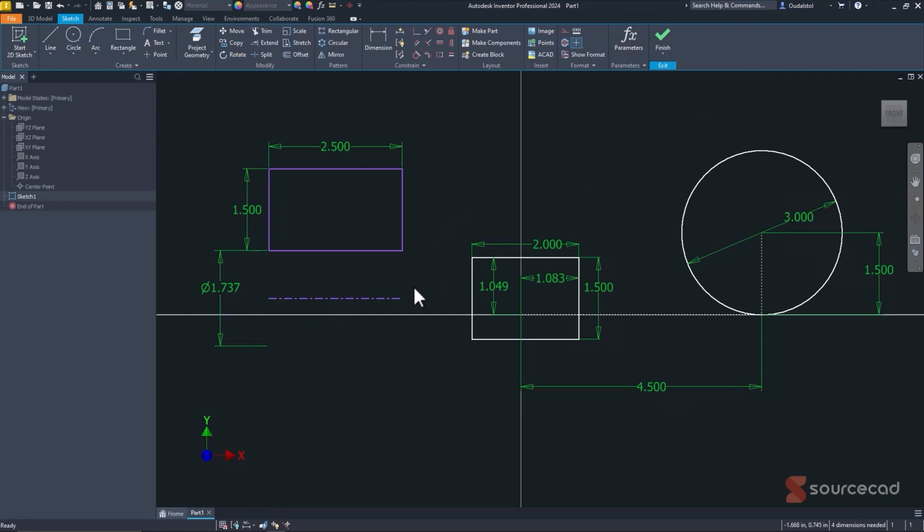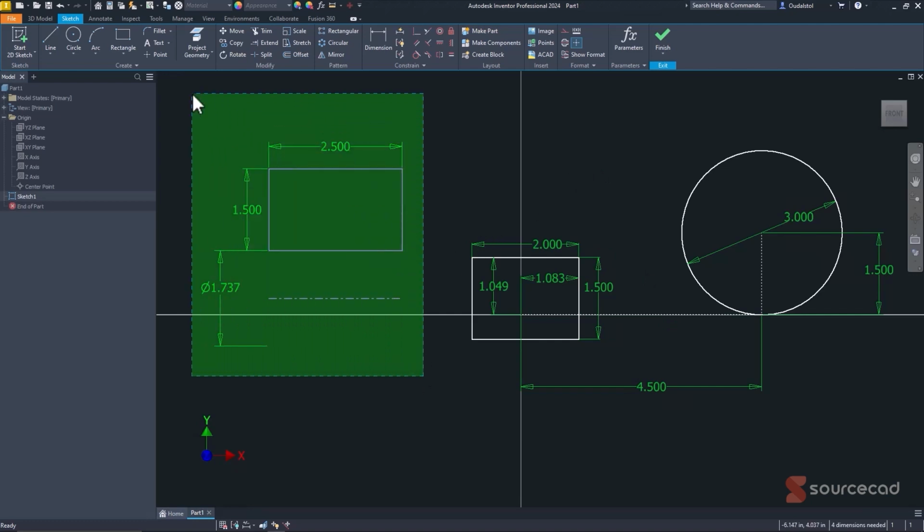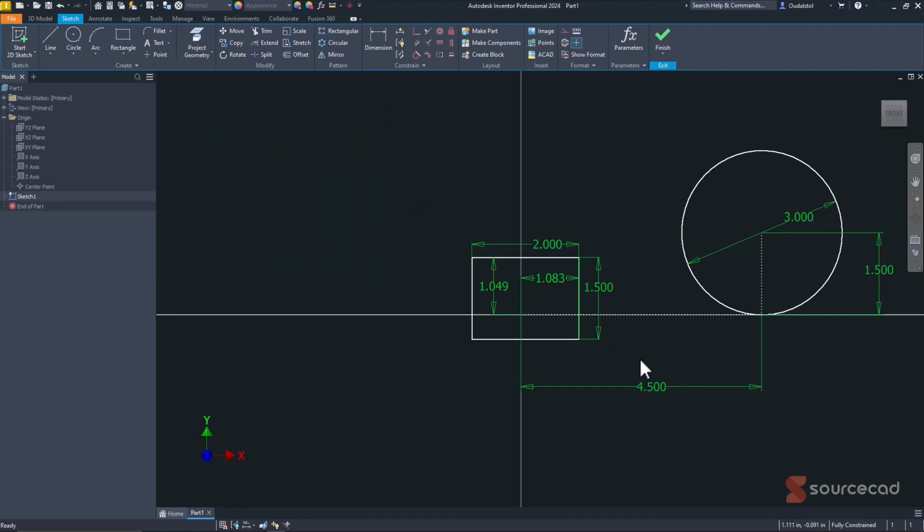Inventor will never understand this as a contour line, as it will these others. I want to say solid lines. You might think of this as a hidden line, if you will, in technical drafting terms. Now let's just back it off a little bit. I'm going to delete some of these sketches right here using crossing selection. That kind of gets me everything.